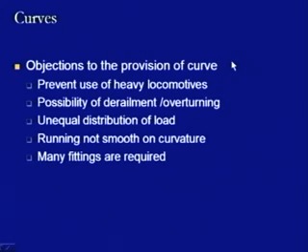As far as the horizontal or straight section is concerned, two things are happening: one is the longitudinal movement, and at some point of time there is a lateral sway or oscillation taking place. But when we come to the curved condition, then there are some more forces working along with the same forces which work on the straight section, and one of those forces is the curve resistance and the centrifugal force.